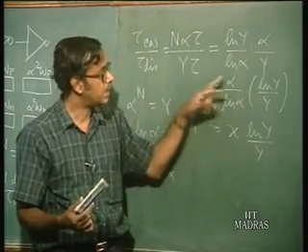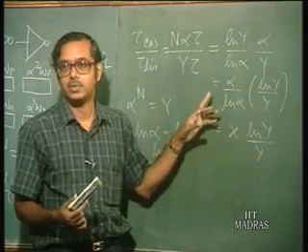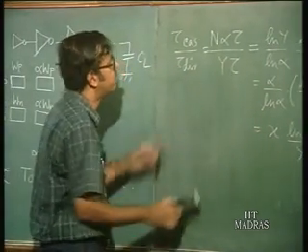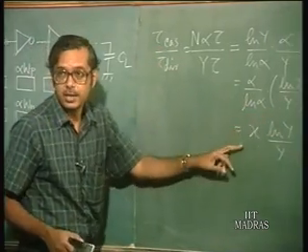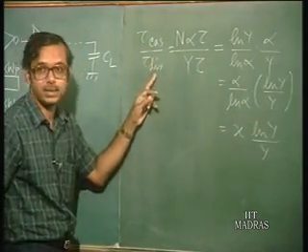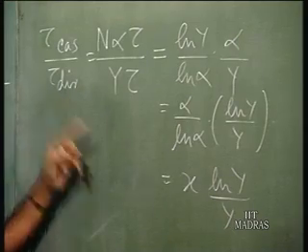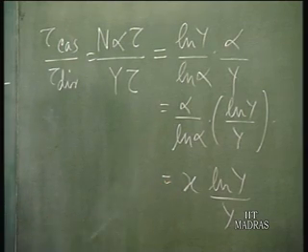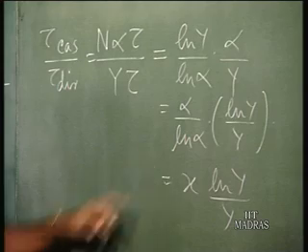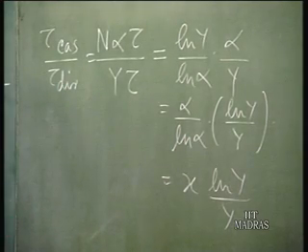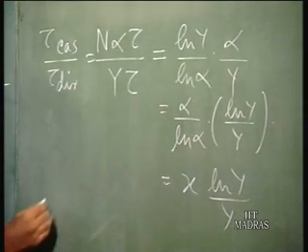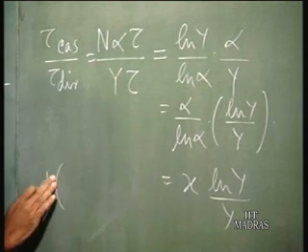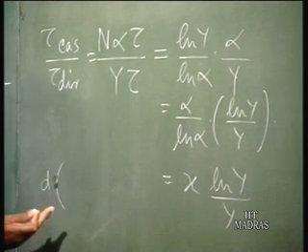So, what is going to be the factor alpha? That is what we have to see. Now, obviously, our aim should be to reduce this as far as possible. Tau cascade by tau direct should be as small as possible. So, we have to minimize the value of x. And what is x? Alpha by ln alpha. So, alpha by ln alpha we have to minimize. We have to differentiate this alpha by ln alpha and put it to 0.